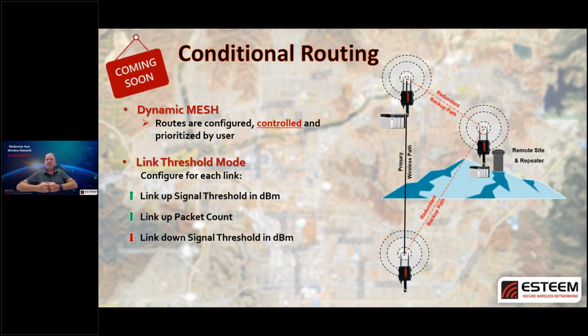So if you get into something where we may have trees growing up, or a mobile meshing type of application, the other reason this is good is that signal strength and data rate are tied. We can set a signal strength and say, I never want to drop below this data rate for things like a camera application, something that is very time sensitive. So we can always maintain that highest amount of signal, which means the highest data rate.